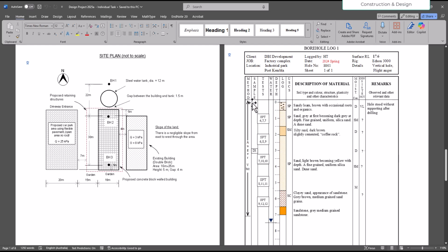So first you have the method. What is the method? Auger bit method. This is used for taking the samples for boring the hole. Okay. Then this is the sample, and then the D1 sample, and then these are the tests performed at these depths.